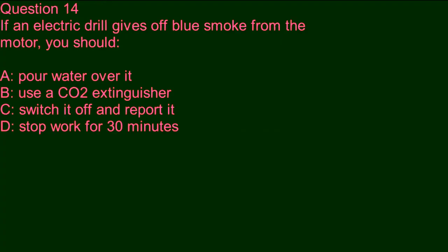Question 14. If an electric drill gives off blue smoke from the motor, you should A. Pour water over it. B. Use a CO2 extinguisher. C. Switch it off and report it. D. Stop work for 30 minutes. Right answer, C. Switch it off and report it.